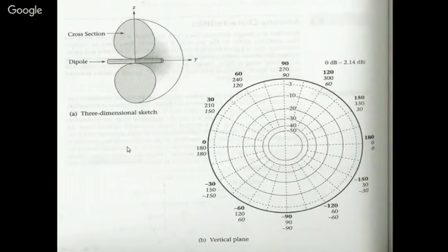And if you rotate in 3 dimensions, it looks like a tire. It means at this place, you will not get the signal if you look in 3 dimensions. In a tire, in 2 dimensions you are getting the signal, but in the 3rd dimension there is no signal. This shows that one dipole is not enough to cover the gap area. You have to provide more than one dipole. And this is the measurement facility, how the actual radiation pattern is measured.